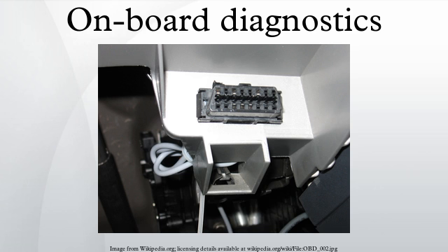J2178-1 defines standards for network message header formats and physical address assignments. J2178-2 gives data parameter definitions. J2178-3 defines standards for network message frame IDs for single byte headers. J2178-4 defines standards for network messages with 3-byte headers. J2284-3 defines 500K CAN physical and data link layer. J2411 describes the GMLAN protocol, used in newer GM vehicles, often accessible on the OBD connector as pin 1 on newer GM vehicles.